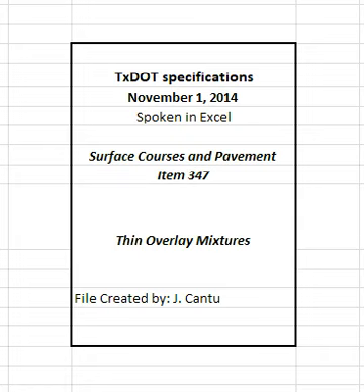The engineer may perform or require the contractor to perform Tex-226-F on Lot 1 production to confirm the indirect tensile strength does not exceed 200 psi if the optimum asphalt binder content for JMF2 is more than 0.5% lower than the optimum asphalt binder content for JMF1.